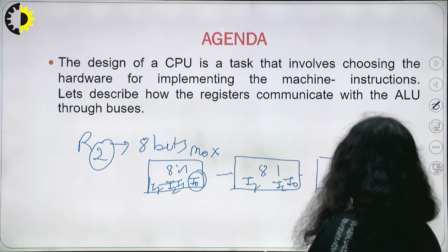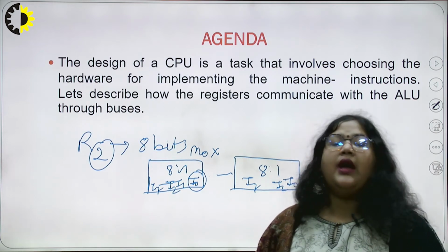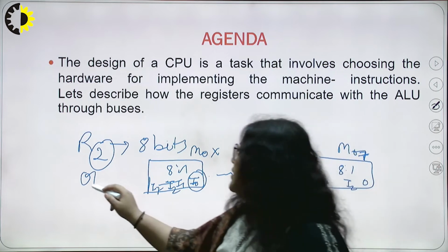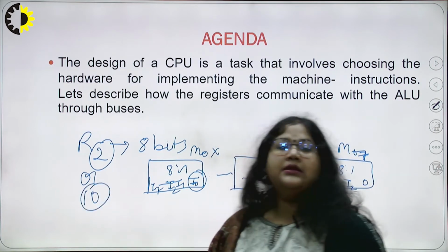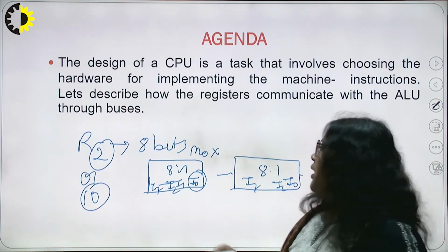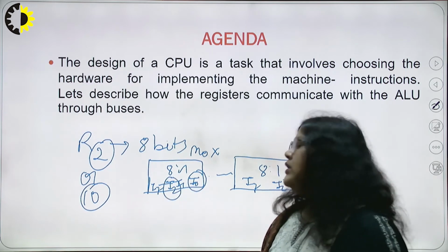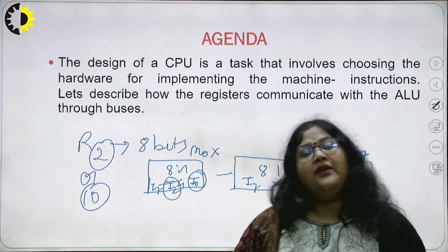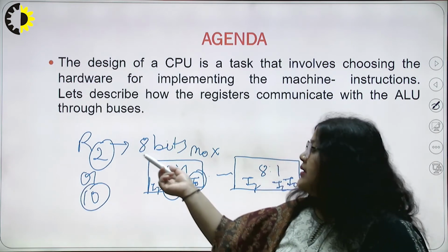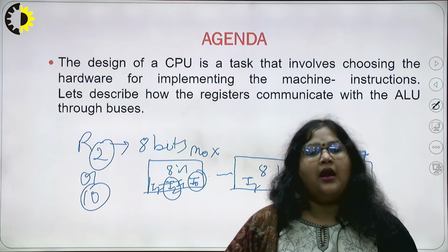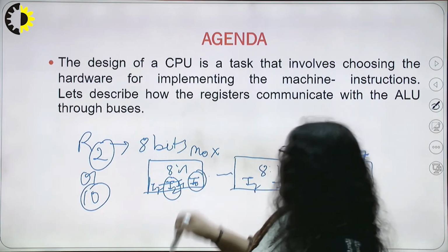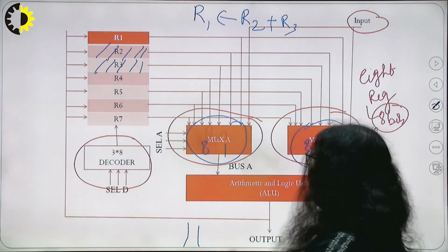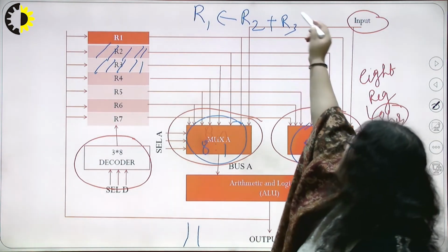So in each mux, input I2 is high, because this is binary 0 1 0, which is the decimal 2. Binary 1 0 means I2 is selected from each mux.